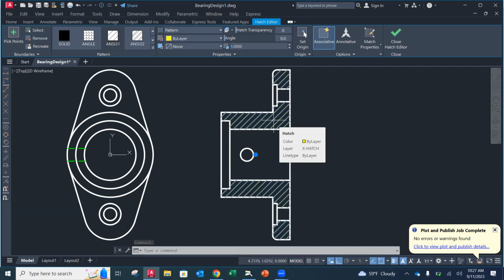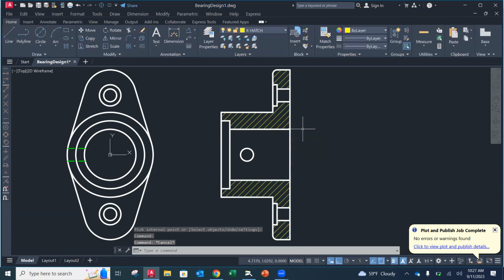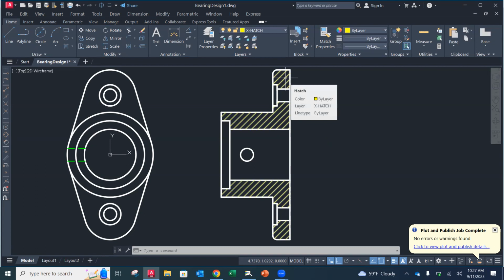Okay. So I'm just going to hit escape. Now, this is where if anybody went into a section and it didn't grab that section, or it went outside of the section and continued somewhere else, that means your geometry wasn't closed, or you didn't have just single lines. There might be overlaps. And that's where AutoCAD gets confused. It's like, I don't know what I'm supposed to do here.